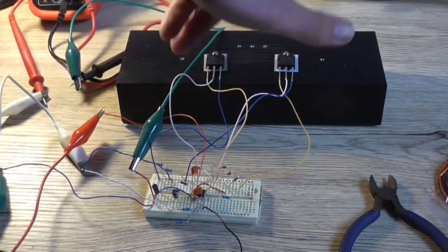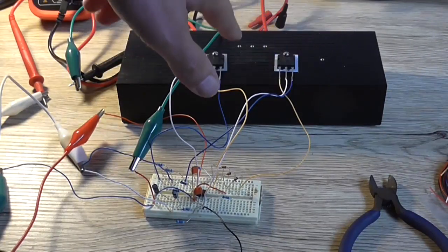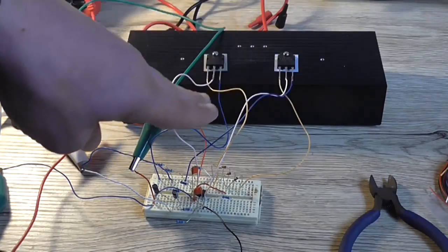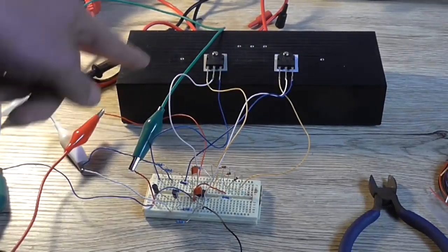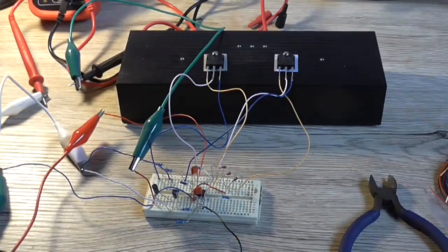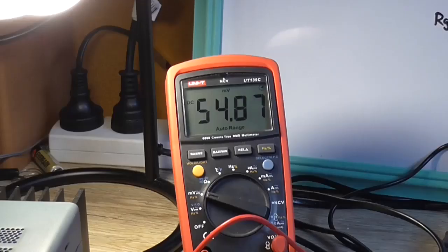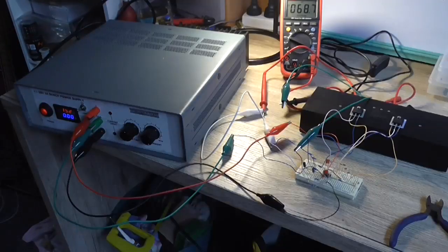I've got the transistors mounted on a heatsink with isolators and wires coming off the transistor leads into the breadboard, because obviously the transistor leads will not fit in the breadboard directly. I've got the power supply sitting there at 15.2 plus minus, and I've got the multimeter connected across the output on the millivolt scale. I haven't powered it up yet, but the only thing that can happen is the output transistors go off with a bang, and hopefully spectacularly.